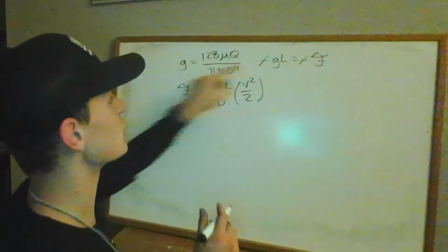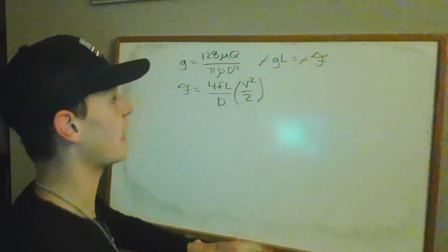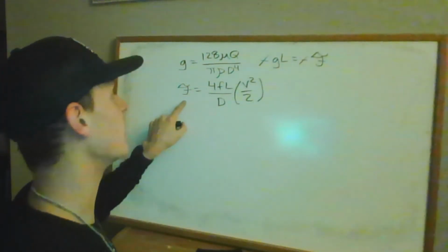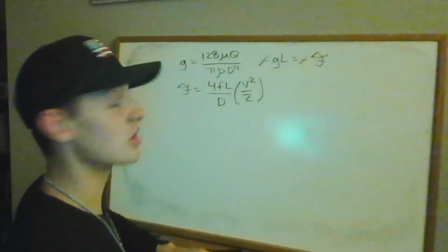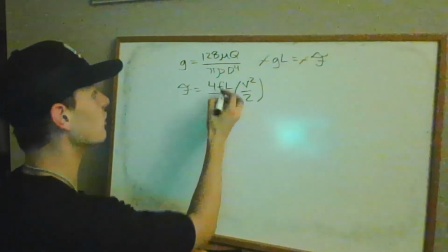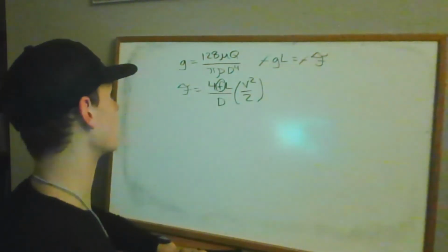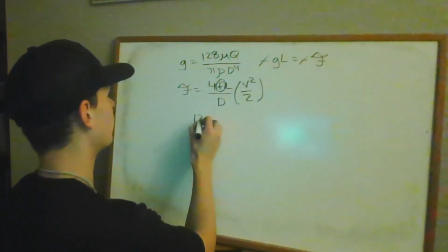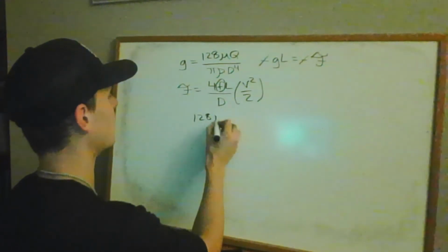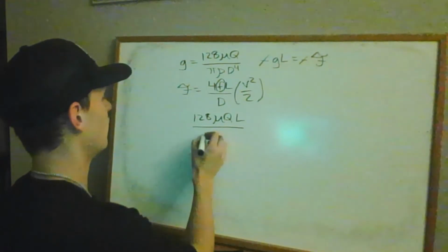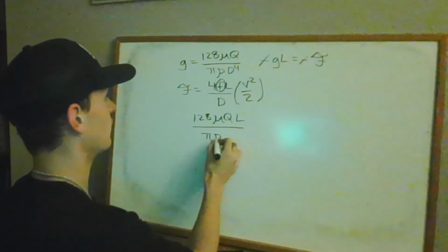So we have the acceleration due to gravity, and we can substitute that in here. Notice that the negative signs cancel. And notice that I've also added here the frictional heating expression that we're going to use that has this small letter f, and that is the Fanning friction factor that we're after. Okay, so using what we already have here, we can express the frictional heating here.